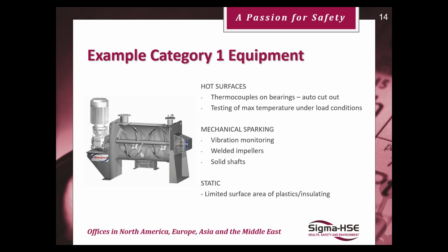ATEX rated equipment. I also just want to add, when you do buy an equipment and it's ATEX rated, it has an EX plate, the manufacturer has also undertaken this same risk assessment outlined in this methodology, this standard 80079-36. And then from there, it's lodged and sent to a technical authority that confirms or verifies it. And then you get the EX plate on your equipment. So yeah, these are just some examples of what a thorough ATEX rated equipment looks like for a complex machine like a mixer handling hybrid flammable materials.